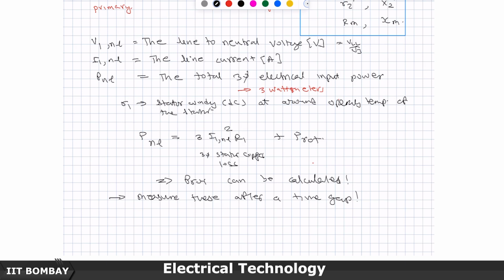So, do not immediately start, measure, and switch off. Start the motor, keep it running for some time, so that the windage losses have settled down, the bearings have become smooth, and there is no instantaneous friction to be overcome. Then measure these losses.